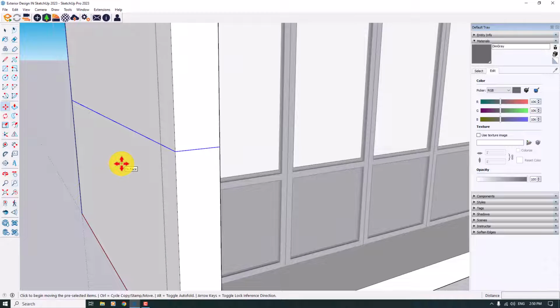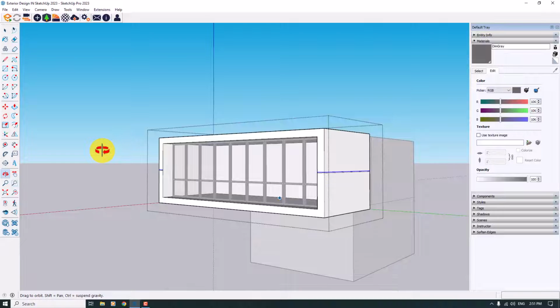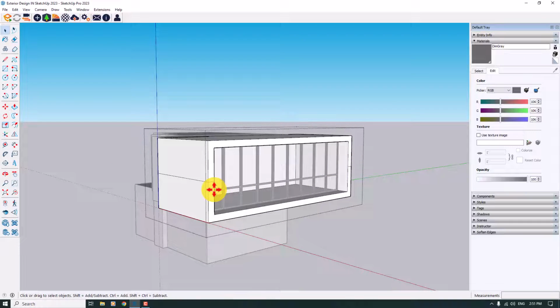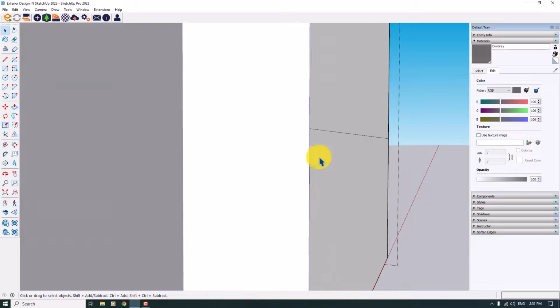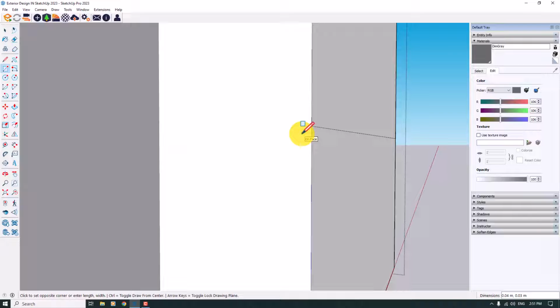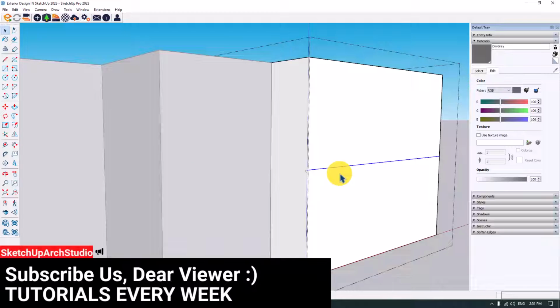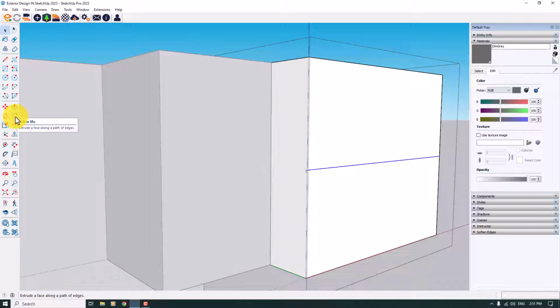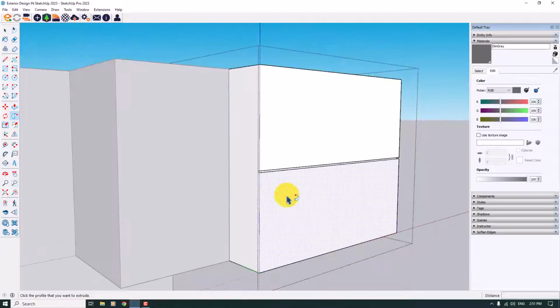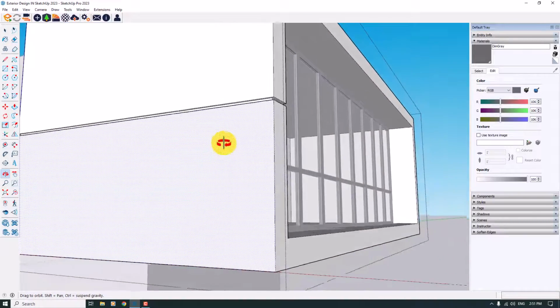The first way for creating chamfers in your SketchUp is that you can take another copy, for example, 3 centimeter. As you can see, you create your chamfer. But the better way for professionals is that you can come to this part of your job and draw some small tiny rectangle about, for example, 3 centimeter by 3 centimeter. Select your favorite lines in there. Now you select your path. So you can use the follow me option in here and select your profile. As you can see, now you have some clear chamfer in this place.